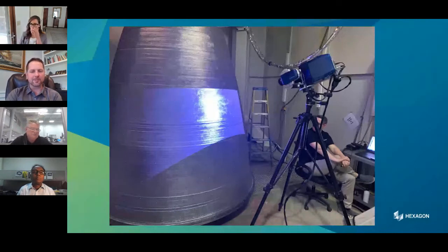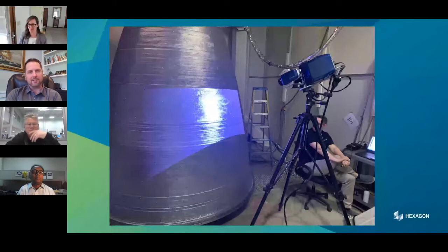So the short answer is that if you have a good material model, like an accurate characterization of the material, and you are correctly capturing the molten region, like how much metal you are melting and remelting on each pass. How we typically recommend doing that is by creating a wall section and then doing a cut and etch. Typically people in the course of their process development will already have something like this done. You do that cut and etch, and then you can measure a number of different beads for the given width and height.